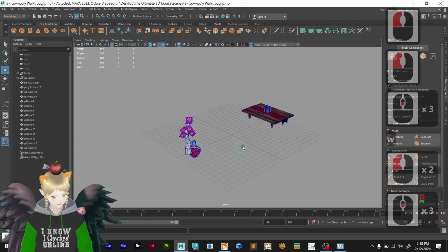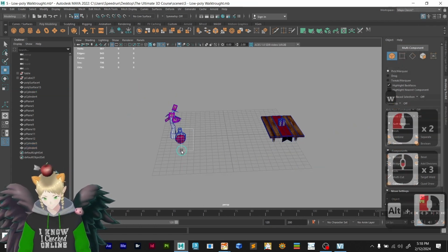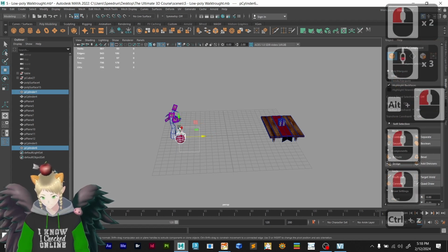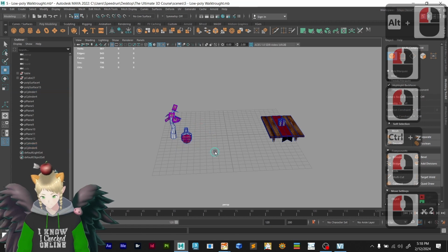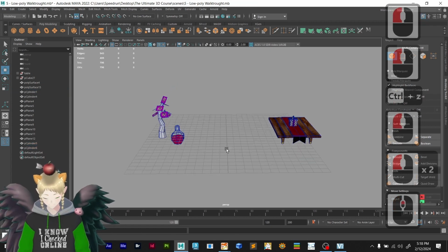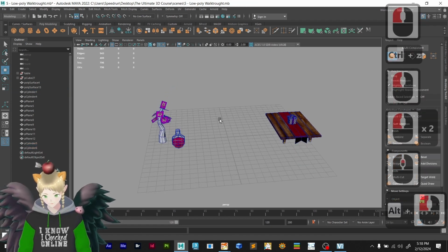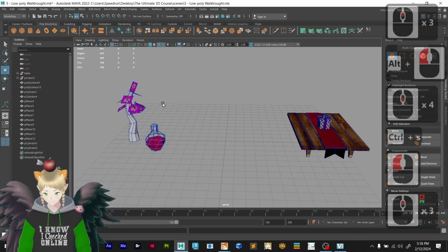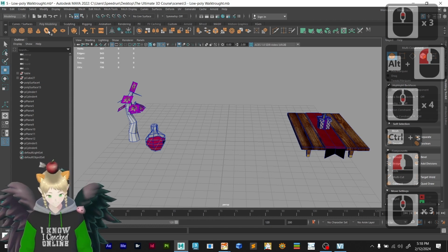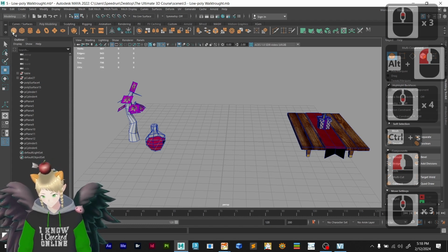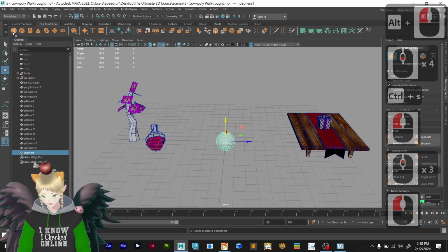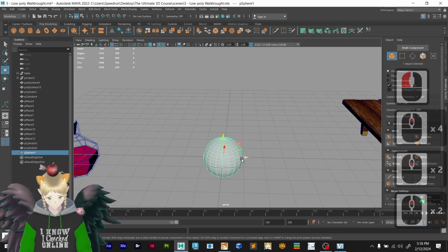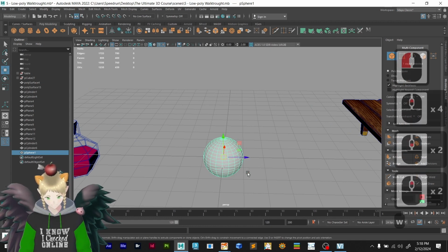Now we just have one more 3D to go. With this, we'll give you enough knowledge on how to create your own 3Ds on all sorts of stuff. You can see we can model anything out of anything in Maya. Next, I'm going to create an eye. So we choose here this, our sphere. Let's keep perhaps high poly like this.